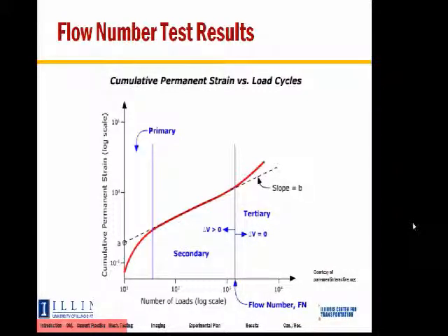If we look at it, in this case, over more than 1,000 cycles, we actually end up defining different zones along this creep curve, the primary, secondary, and tertiary zones. Okay, we have an initial response where we see a fairly rapid accumulation of that permanent deformation. And our secondary zone in the middle is where we have a relatively constant permanent strain per cycle.